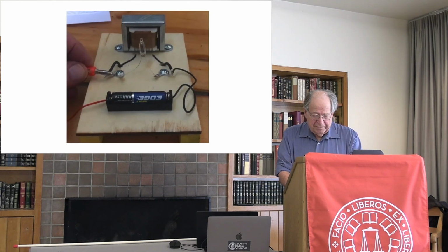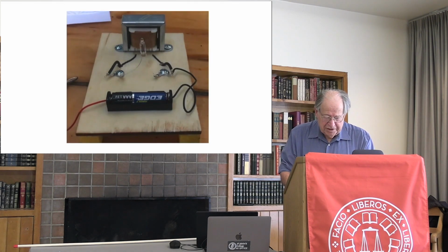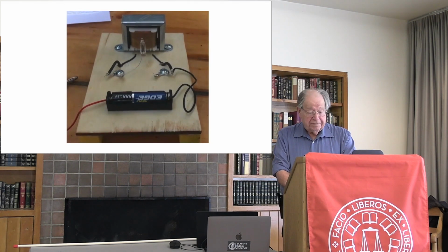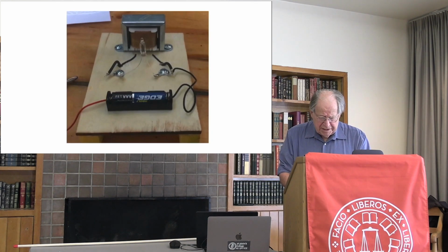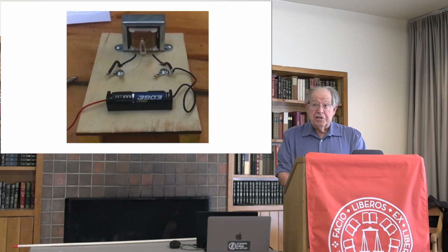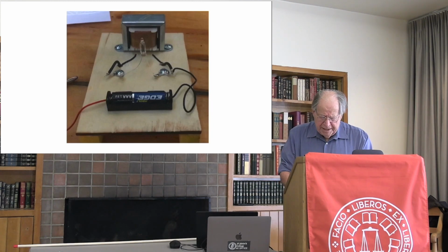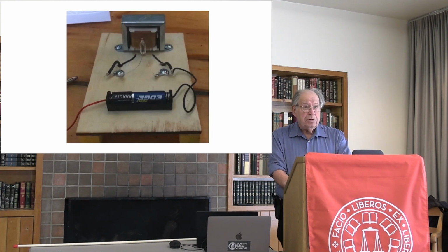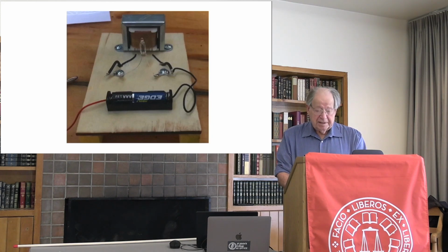Evidently, the coil developed a sizable voltage, much higher than the voltage of the battery itself, and sufficient to light the bulb. But what is important to us is the fact that this occurred at the moment the connection was broken. That is, in conjunction with an abrupt cessation of the current. It seems that the act of winding a conductor about an iron core makes the moment of change especially significant.